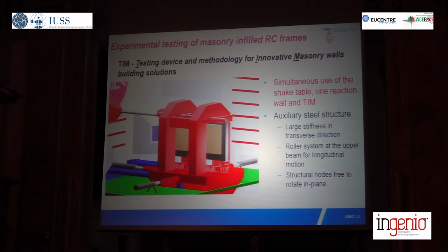So the idea is that it transmits the out-of-plane motion of the shake table to the upper beam of the reinforced concrete frame, such that the reinforced concrete frame moves as a rigid body, and so you have the infill wall only vibrating, or having the freedom to vibrate, relative to the reinforced concrete frame.